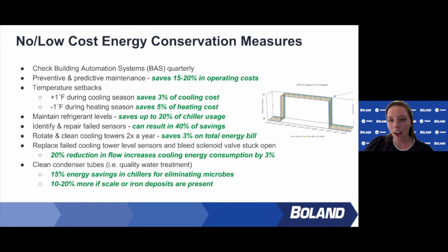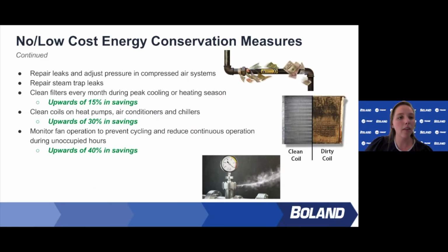savings. A few more. We have continuous no cost, low cost opportunities. Cleaning your filters can save 15% of energy depending on how frequently you clean them. I love this picture. You don't want a Band-Aid solution for a leak, especially with compressed air or steam systems. Any sort of leak is literally money just blowing out. So if you can work on that, it will pay back very quickly.